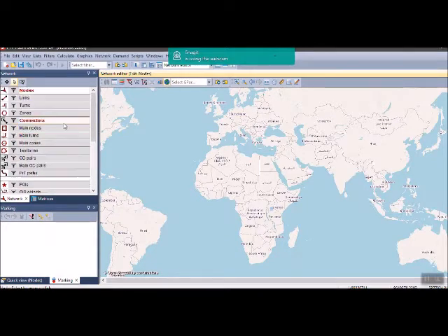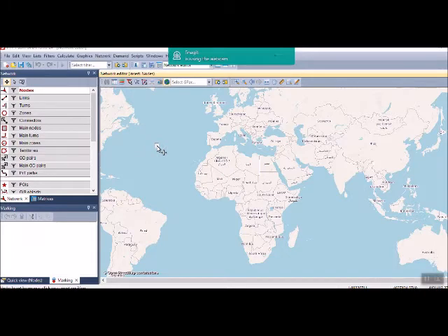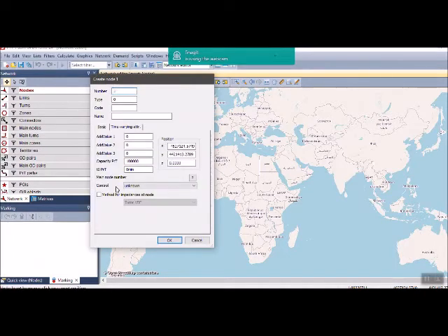First of all, you should know that you have two main icons here. The first one, which is the plus icon, allows you to add any item to your network or to your model. And the second is the edit mode. So when I choose, for example, a node and select the insert mode, and when I click like that, a new node will be created.